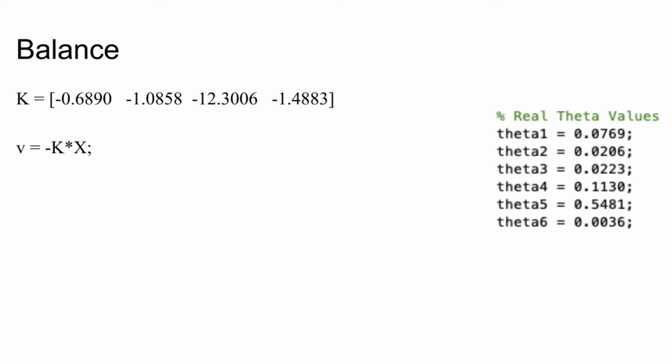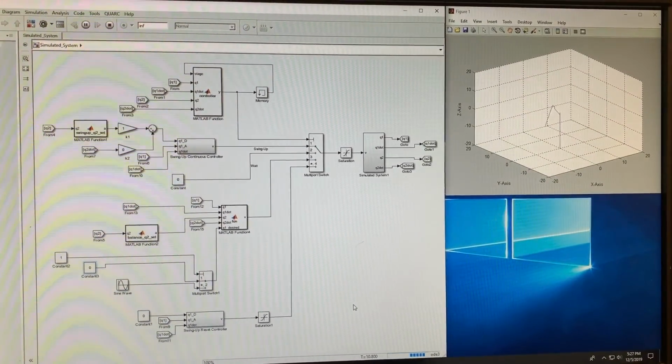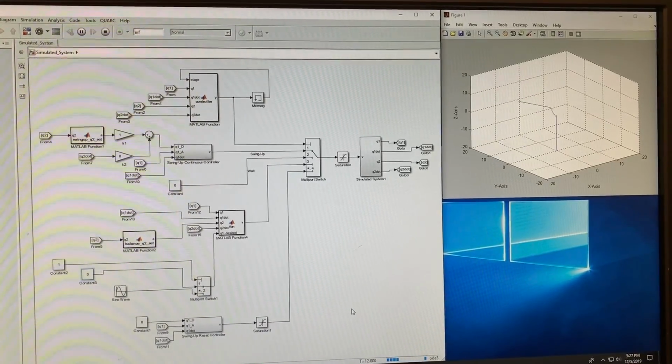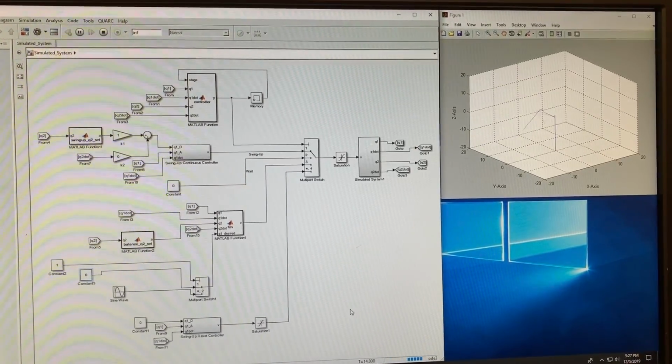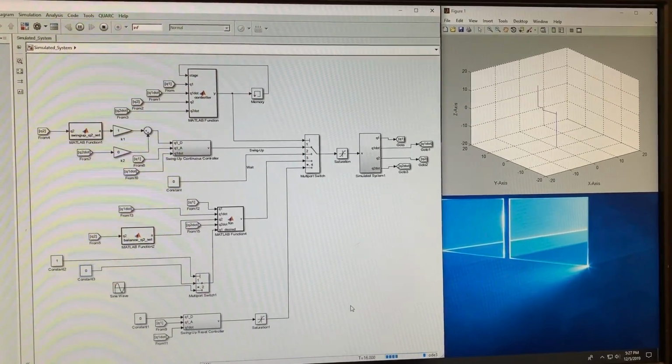In addition, it was possible to balance a pendulum by using different values when placing the poles. However, the poles that we decided on were -5 because we believed that it created gains large enough to create a robust control of the robot so that it would better counter attempts to push it over. We were therefore able to successfully create a smooth and reliable swing up and balance from start as well as from being knocked down.